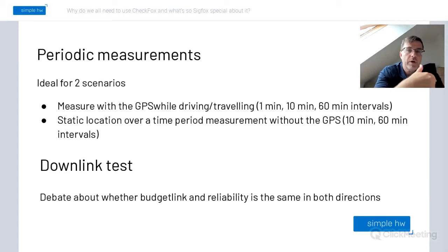Therefore, for instance, in the Czech Republic or in Switzerland, we are building the network in such a way that you always have multiple base stations covering the highway. We are also doing highway coverage at minus 30 dB margin. We are also trying to put the base station not directly on the highway itself, but perpendicular to the highway, so the fading effect is not that pronounced. And once the car reaches over 60 kilometers per hour, again the fading is not there, and Sigfox works pretty well.